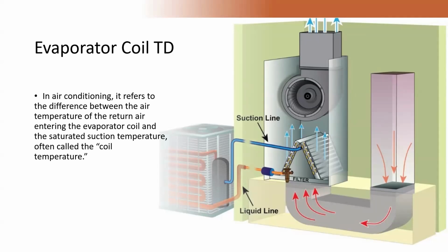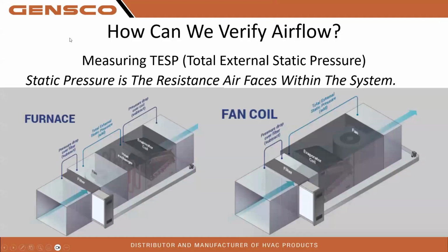So we talked about refrigerant flow. We talked about latent load. We talked about sensible load. We talked about the importance of having proper flow and proper airflow across the system. Now we're going to talk about airflow. We're not going to dive into this too much, but I get a lot of people when they say the airflow is good, or it's a 3-ton unit. I set it at 400 CFM per ton for a 3-ton, so it's moving 1200 CFM. Is it? Right? You can trust what it says, but you should really verify it.